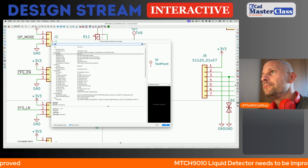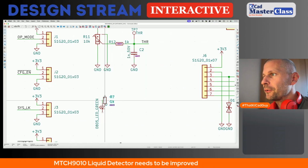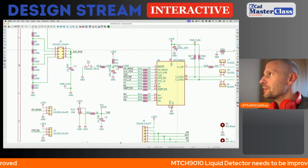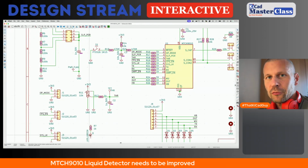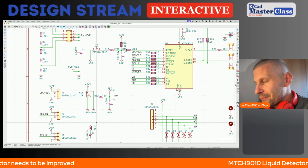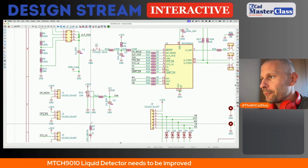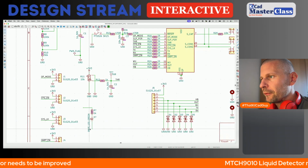So 1K will be the resistor for the LED. It means that when the IC is supplied from 3.3 and the forward voltage of the LED is above 2 volts, the current will be just about 1 milliamp. It can be 1K5, but I will use 1K. Okay, and here will be ground.